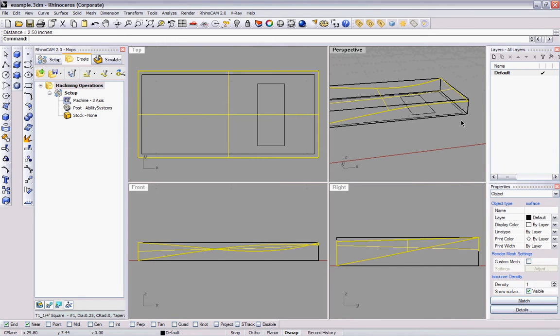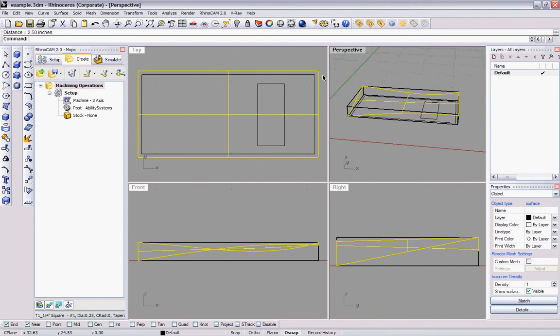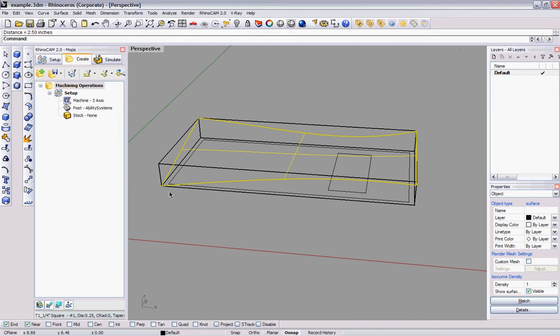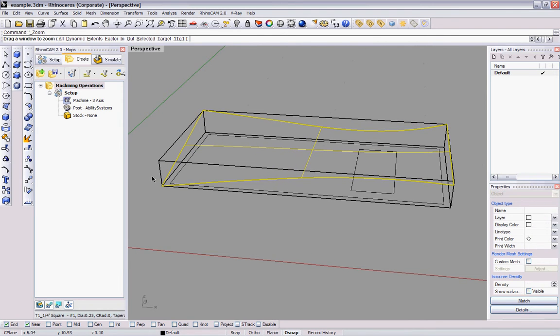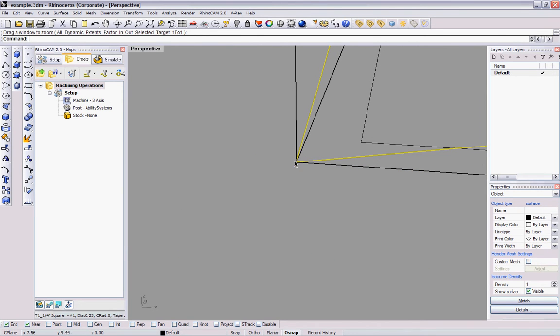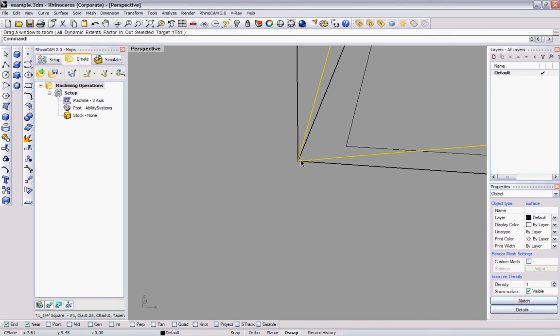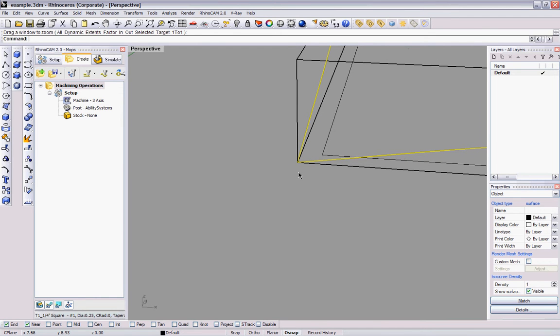Okay, so I'll take a few other glances. So this is a concern here. This corner goes all the way down to z equals 0, which is the CNC table surface. When you get that thin on the material, the bits tend to blow out the material there, meaning it rips the corner off and does not give you the clean geometry you're looking for.